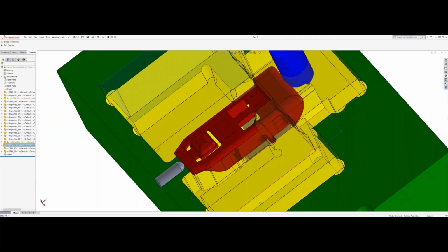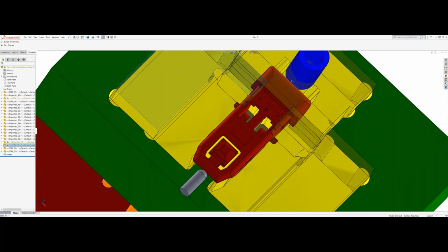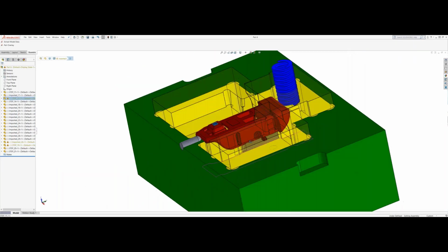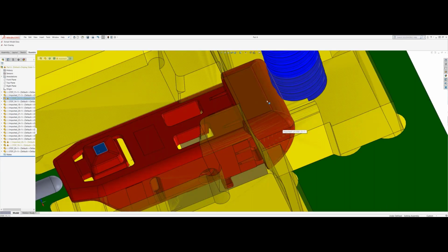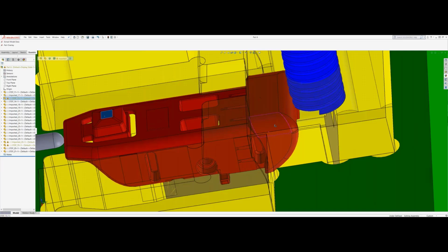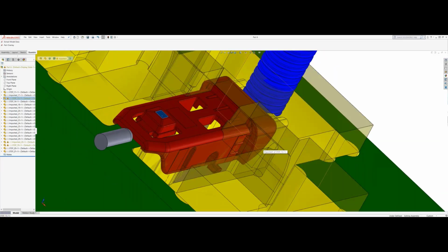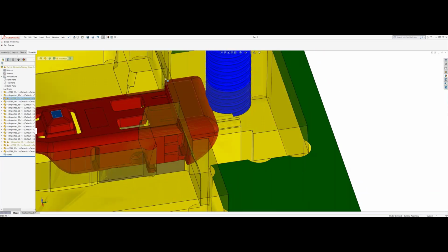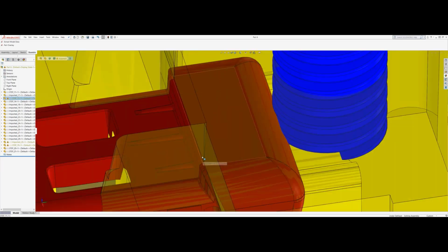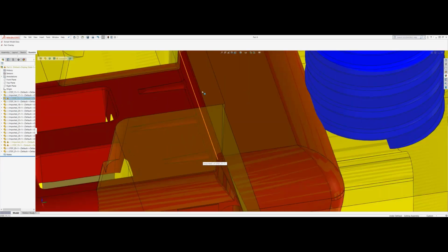So this one's not too crazy. I mean, the only thing we had to do, being that this area of the part was cosmetic, but that's being captured by the cavity side, and the other exposed area is this area in back here. So that's why it's pretty much embedded into this action here. So you would not see any seam lines, and the only seam line here is going to be kind of hidden in this radius.